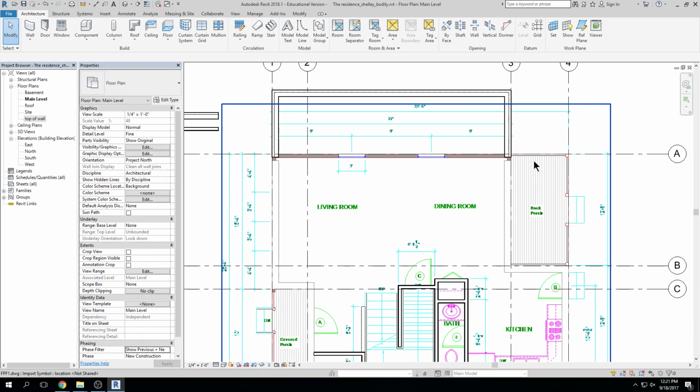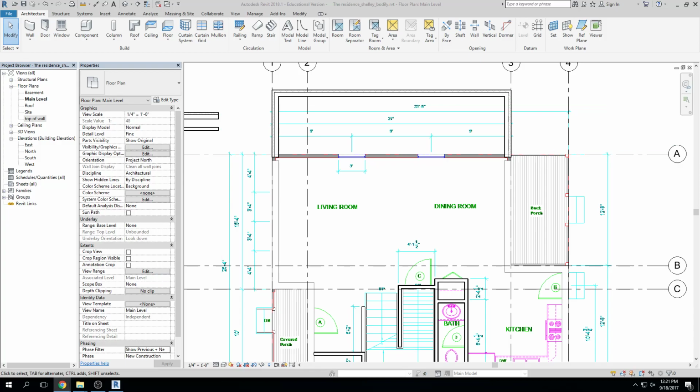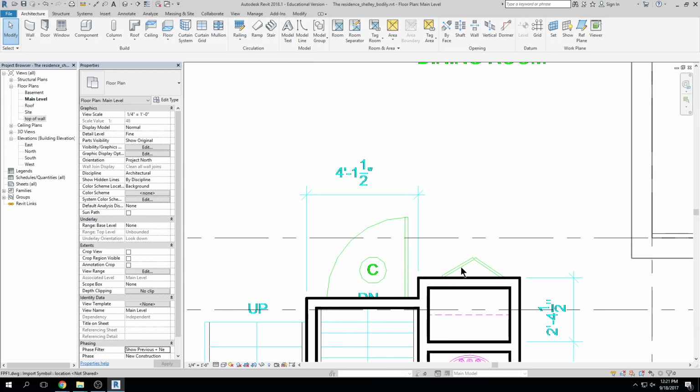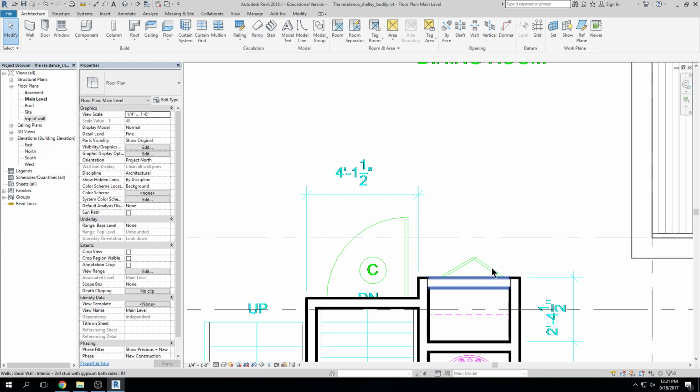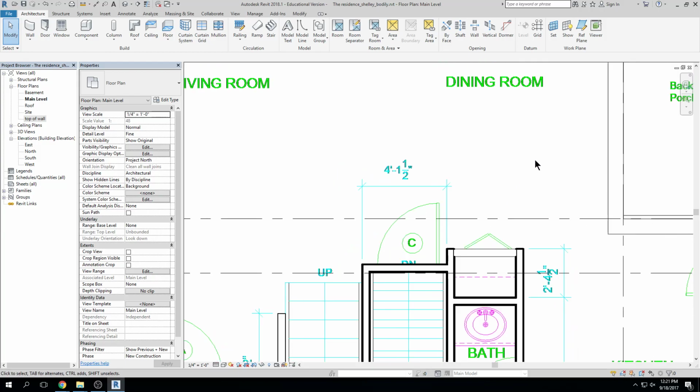I think for this assignment, I maybe had you work with the phases. Not manipulating them to this extent, but, let's see. Yeah, I want you to put everything on an existing phase. Okay, so that just means that if you draw it, when you're done, you could grab it and click on existing and it appears existing. And you'll be able to tell because it will be shaded gray tone instead of dark black.